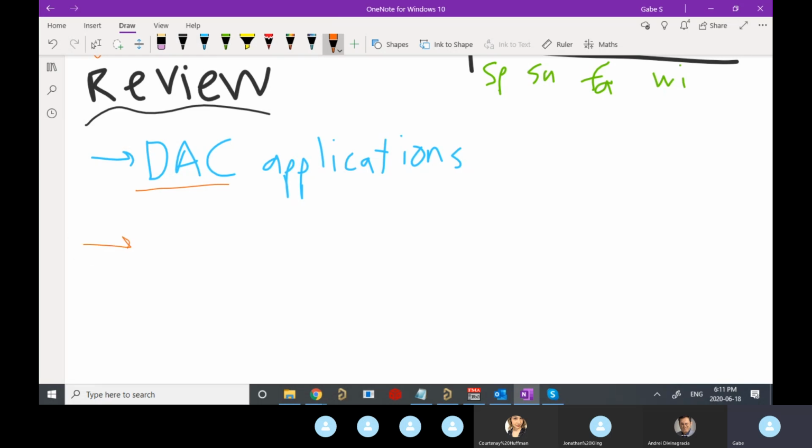So far, we've also talked about in these sessions GPIOs, right? You have inputs, outputs, pull-ups and pull-downs. And then on your outputs, you can be push-pull, which means you are outputting a high to your logic level and a low to ground. Or you can just be open drain, where you're only sending a low to ground, and then for your high, you just leave it floating. And usually you want to accompany this with a pull-up resistor.